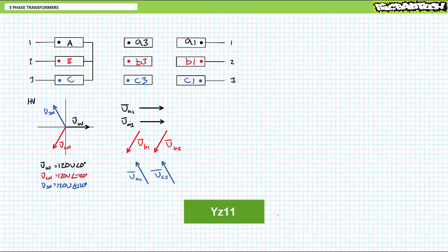I found one way of effectively illustrating the result of a zigzag connection is to first draw the phasors for each low voltage winding independently rather than grouping them on one diagram. I should additionally remind you that not everything you see on the internet is true. Case in point, there are startlingly incorrect depictions of zigzag connected transformers floating around out there that sometimes appear in otherwise reputable trade magazines and textbooks.